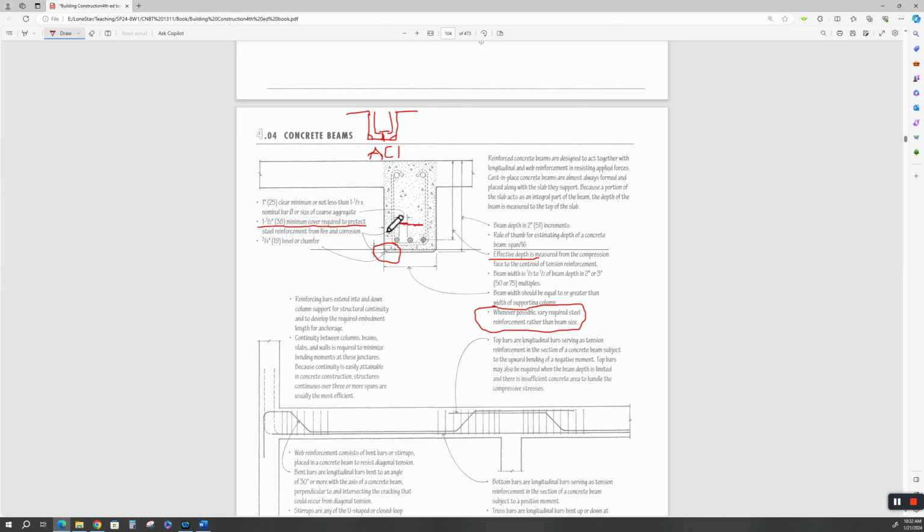You've got to have the coarse aggregate and all the aggregate get in there when they run that vibrator spud down in here while they're casting it, to vibrate and get a good dense fill. You want this really dense, and that's why they vibrate it with those spud vibrators while they're casting, because you want that concrete and that aggregate to get all around that rebar so you can have good adhesion, because that way it acts as a unitized device.